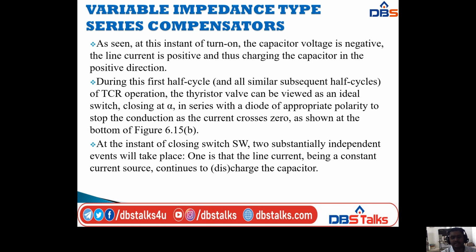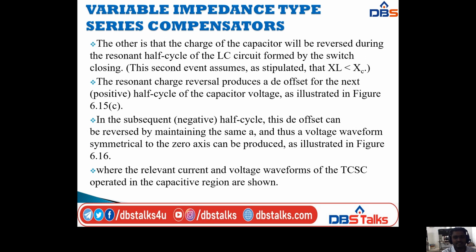One is that the line current, being a constant current source, continues to charge or discharge the capacitor. The second is that the charge of the capacitor will be reversed during the resonant half cycle of the LC circuit formed by the switch closing.